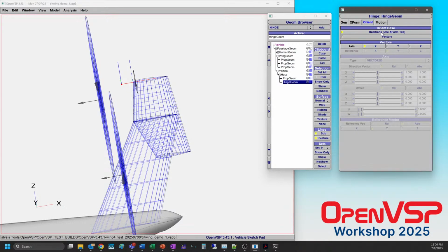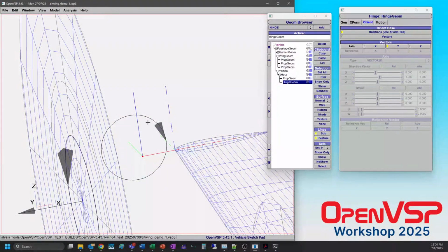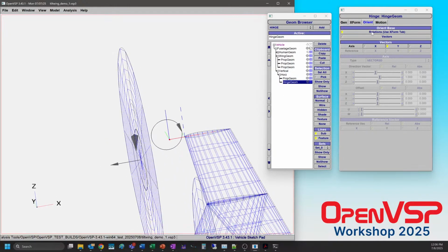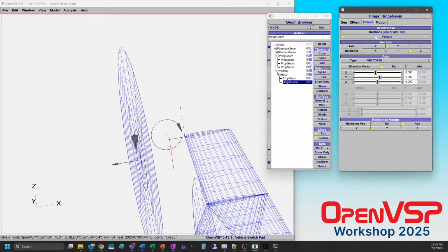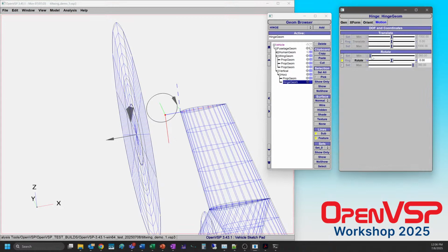Now that we have this geometry, we need to pick a direction. So instead of using the transform tab, we're going to use the vectors. And in this case, we want to rotate about the y-axis. That's going to be this green line we have here on the screen. And positive rotation is in the direction of this arrow. Okay. So we could just leave it as is. We can choose a vector. And here, notice that everything has turned. We've got rotation of y equals 1. Good.